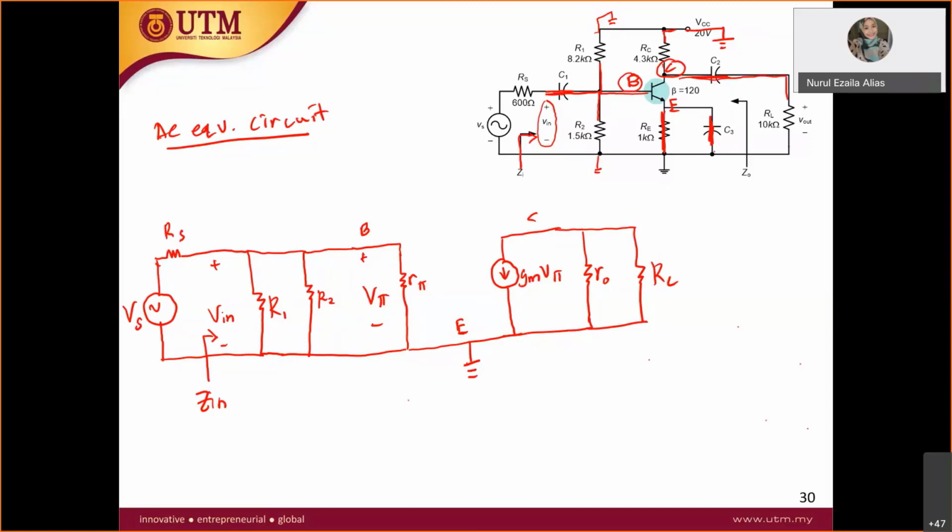Like I said, most of the amplifier circuits have an output load resistor, which is RL. At RL here, you have your V out, put all the notation. Look at the Z out arrow. Z out arrow is before your RL. So Z out is not here, wrong. So Z out is before RL, which is equal to this portion. Z out is equal to RC, like that.